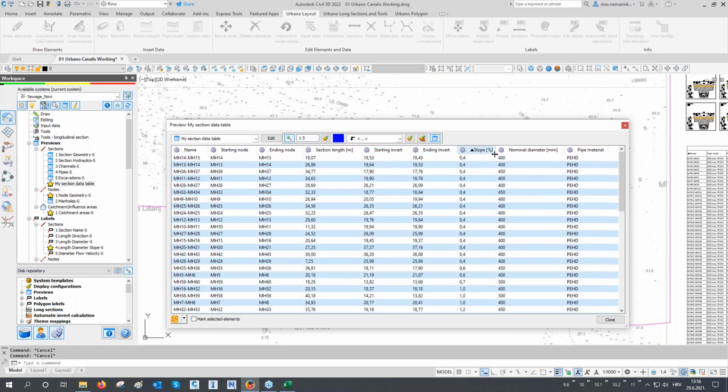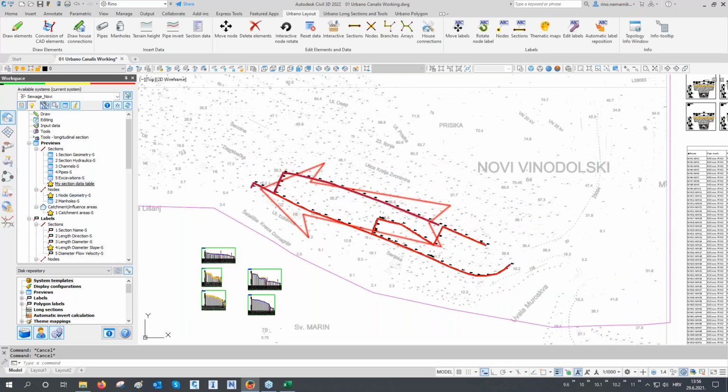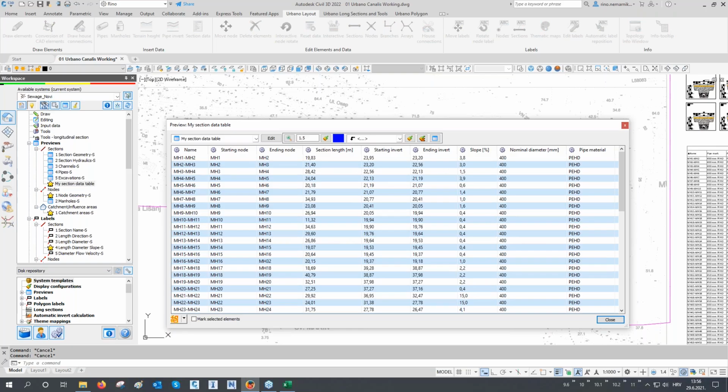So this is also really nice if you always would like for your data table to open like this, for example. And remember, if you change something, for example, this column width, do not close it with X because it will not be saved. Close it with close button. And now when you open it again, this is it. This is the data table.